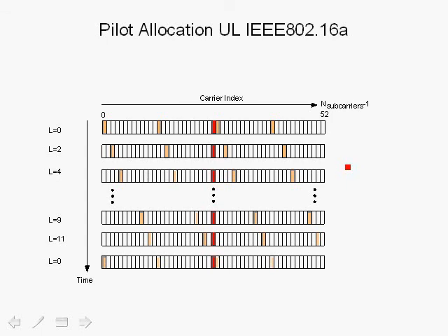And also in a fixed wireless network, this is very important because, again, we achieve diversity, where if we had a deep fade, for example, all the pilots would not be eliminated. If they were fixed in that deep fade location, because of the fact that they're variable, then we have a diversity effect. So we have a diversity gain in this sense, even for fixed wireless networks and also for mobile wireless networks.